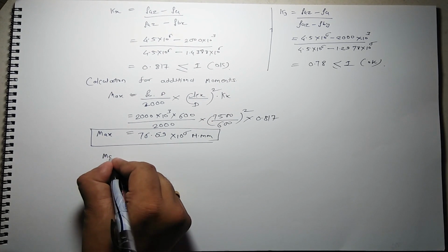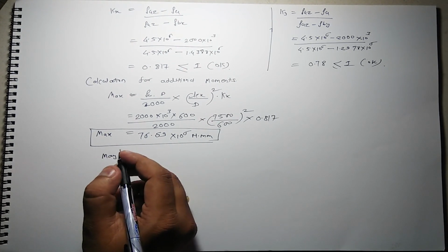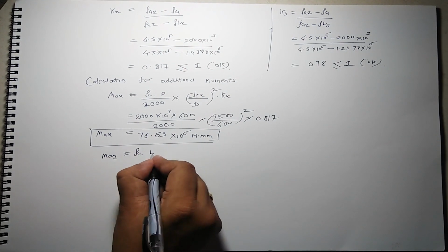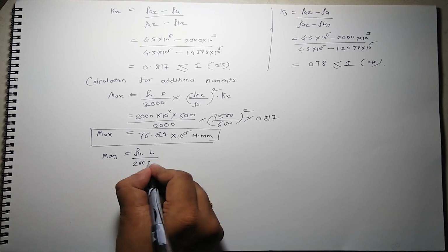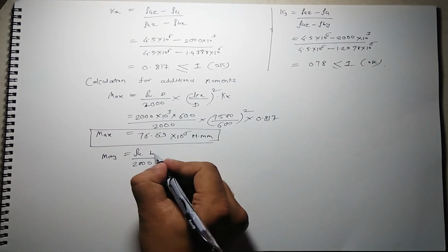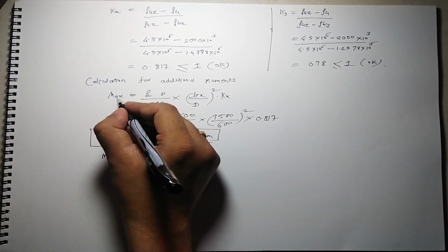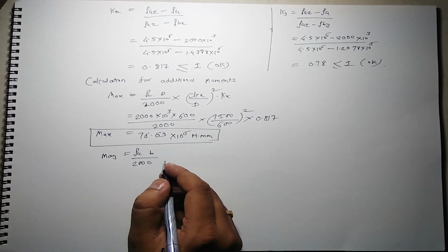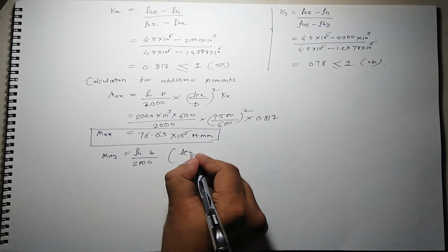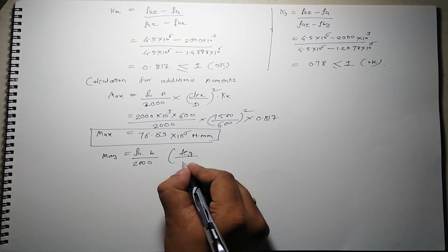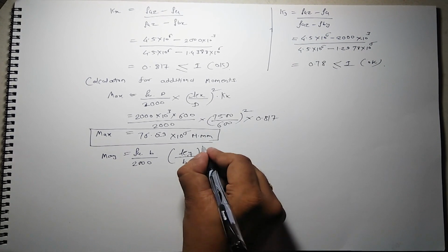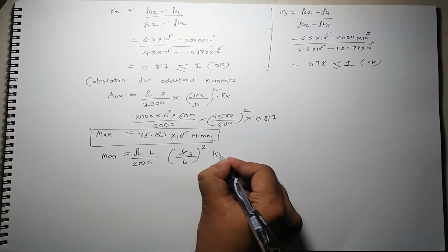Now for the y direction, Pu into b, so you will get D in place of x and b in place of y. Wherever there is a y term, you will get small b, and where there is an x term, you will get capital D. So it is easy to recall: LEY, effective length in y direction, upon small b whole square, into Ky.